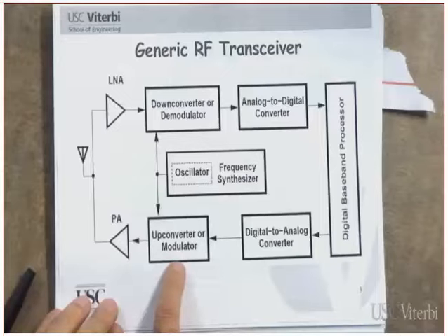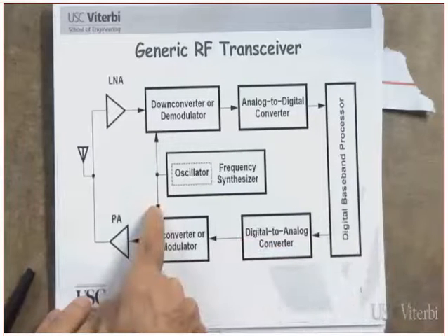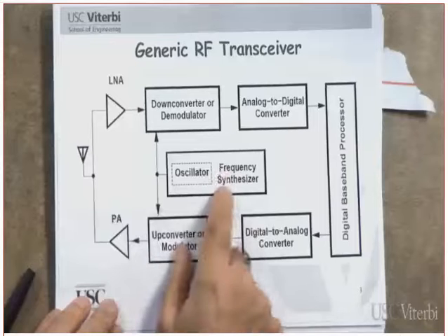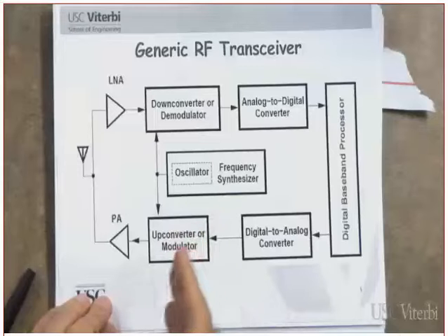How many inputs does the modulator have? It has 2 inputs. One is the baseband, the other one is the carrier. Clear? From a local oscillator. This is a frequency synthesizer, the oscillator here, so it's a variable, voltage controlled oscillator. Why do we need to modulate? We need to answer that question in a minute. Just give me a minute.